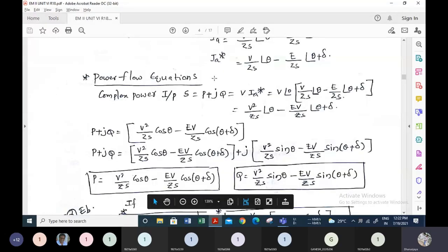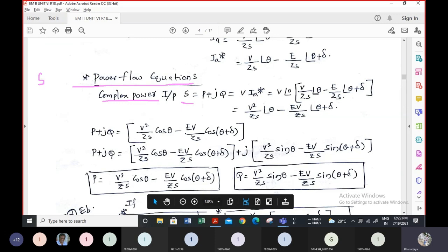We have derived this IA conjugate. So I'll try to substitute here in the equation, and write the expression. Whatever we have discussed already for DC generators and synchronous generators, the same we are discussing for the synchronous motor also. The only relation is everything is same. In the synchronous generator, I represented E equal to V plus IA into ZS, and from that I represented the IA value, and from that I converted it into IA conjugate.